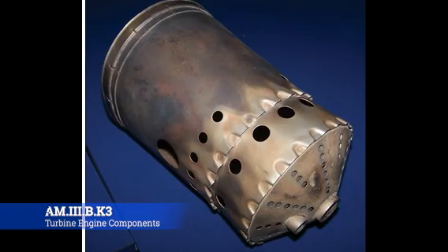So the liners of these can-type combustors have these perforations. You can see the holes going all the way around them. They're all different sizes, and each hole has a very specific purpose and an effect on the flame, the shape, and the way it moves through the can in the liner. So the air entering the combustion chamber is divided into proper holes, louvers, and slots, and there are two main streams it's going to divide up into: the primary and the secondary.